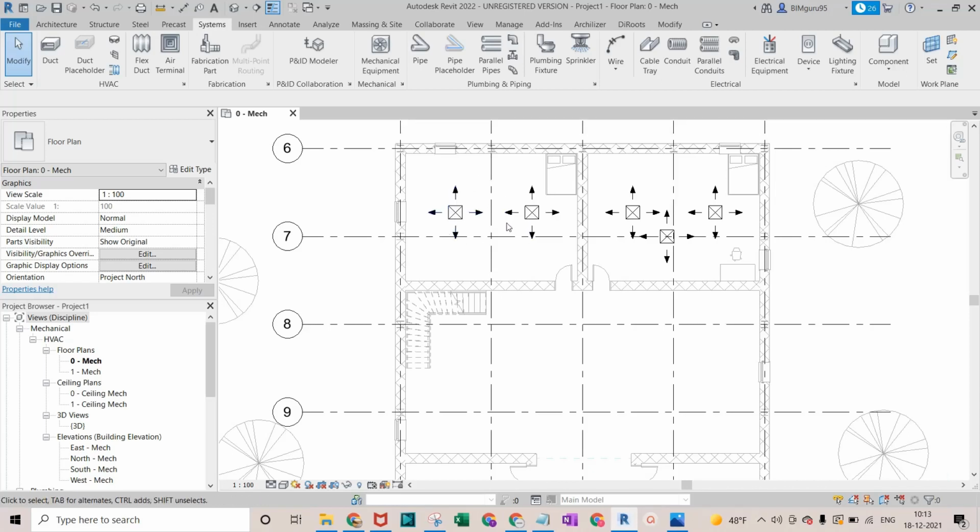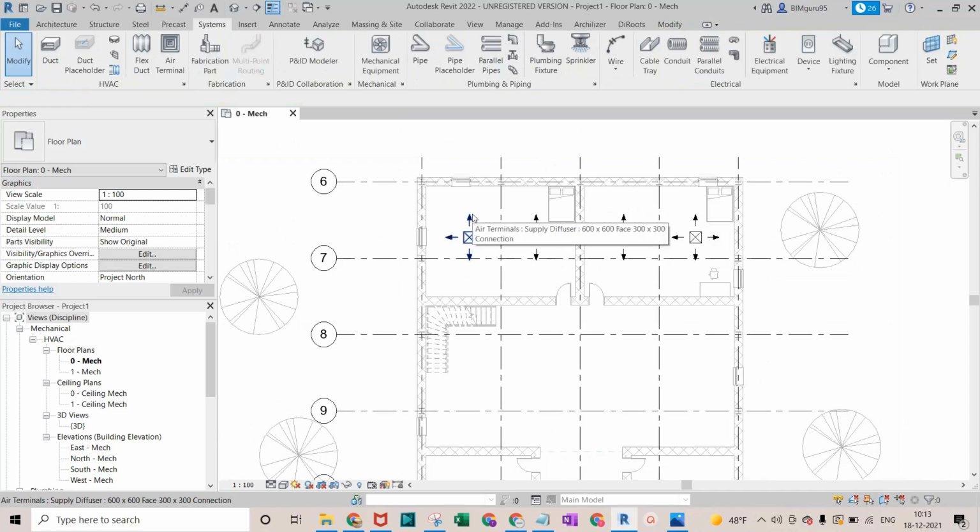Air just exhausts. But we are not exhausting that much air. We want fresh air in this room. So we'll definitely exhaust the air in a bigger amount, but we'll add fresh air as well. So this will be negative, and then again this will be negative. This should not be right, and to balance that, we are using the return air.